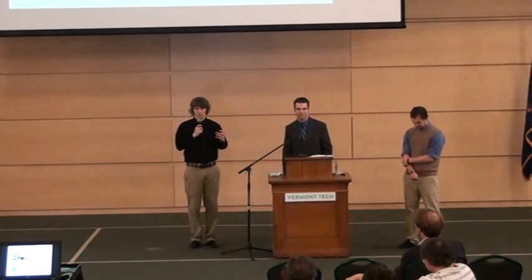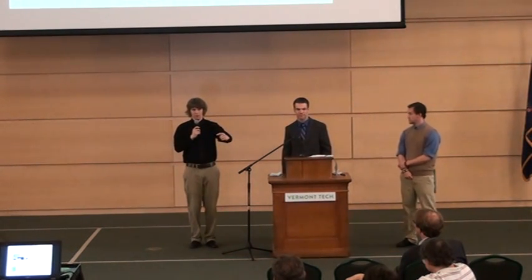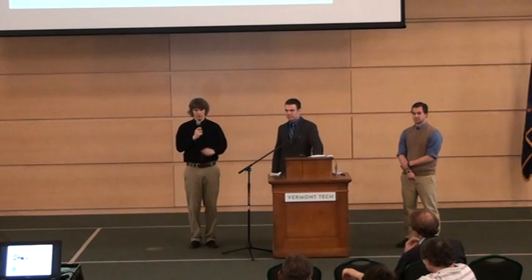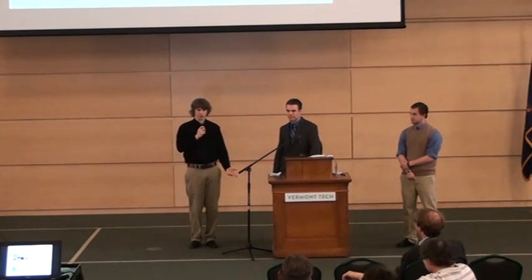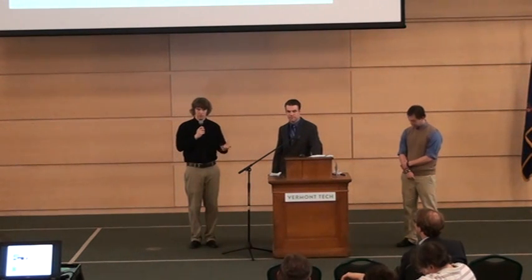Mainly what they wanted to know was that their current method hooks all the cables that are being tested in series. So if any one of the conductors inside any one of the cables fails, the entire machine shuts off, and you have to check each conductor in each cable to see which one actually failed. This checks all the cables at once, so if one cable fails, you can just check the conductors in that cable. But they do an ohmmeter reading of the resistance of the conductors before and after the test.